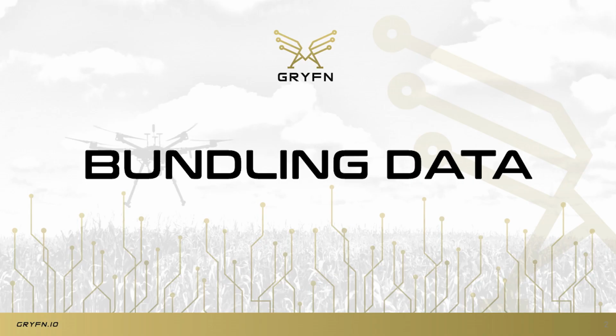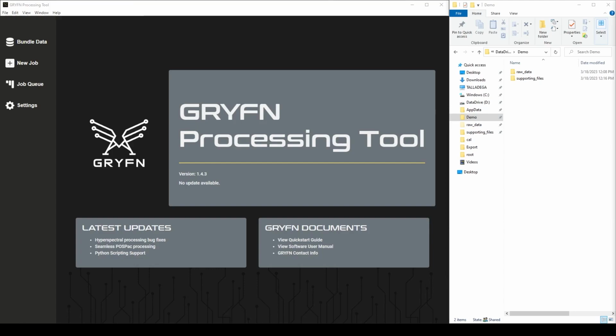The GRYFN Processing Tool is a powerful software solution specifically designed to process raw sensor data from hyperspectral line scan, LiDAR, and high-resolution frame cameras, converting it into orthorectified products such as geotiffs, Envi rasters, and LAS point clouds. To ensure efficient data management and maintain a well-organized workflow, the GRYFN Processing Tool starts by bundling raw data into GRAW folders. This bundling process consolidates all raw data files and their associated metadata into a single, easily manageable folder. By storing relevant metadata alongside the raw data, the GRAW folders enable users to keep track of essential information such as acquisition team, sensor type, and weather details, streamlining the data processing pipeline.